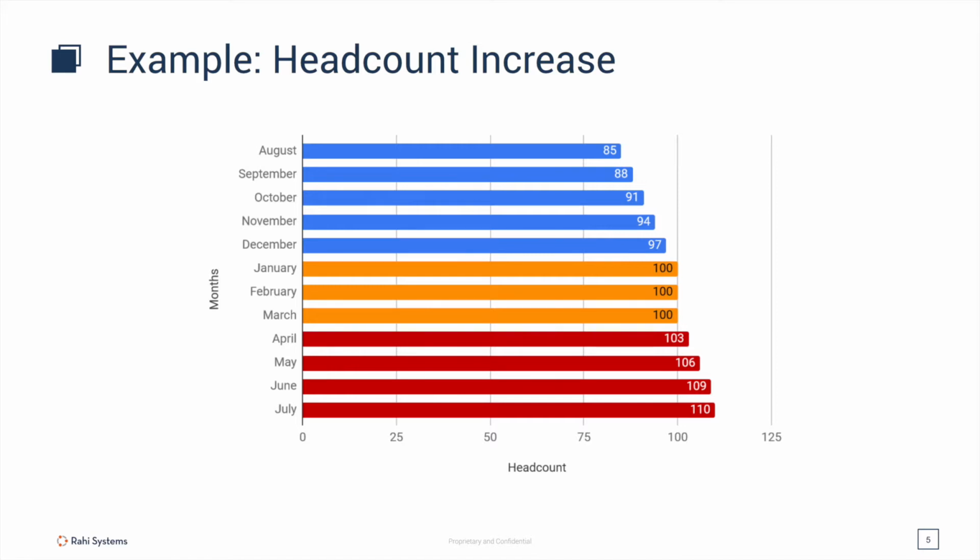Let's take a look back at those numbers. At 200 square feet per person, your ratio of employees to conference rooms is approximately 10 employees for every conference room. At higher densities, you're closer to 7 employees for every conference room. The 7-to-1 ratio necessitates a higher quantity of smaller room types, and some of those rooms are more likely to be meeting rooms instead of conference rooms.